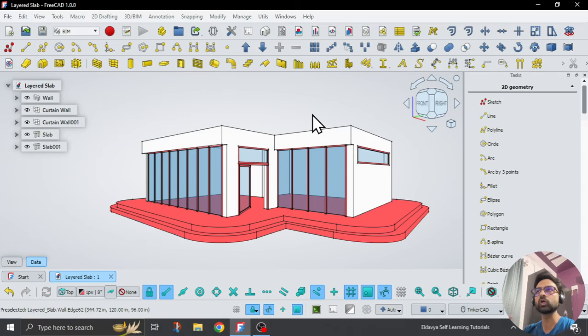Then on top of it you add a very thin layer of bitumen solution just for waterproofing. Then you add some thickness of soil just for better regulation of the temperature inside the house, right? So that's a layer which is required.